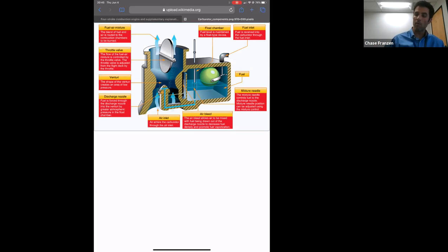Normal position is both, and that's just a very simple 4-way selector valve on the bottom of that fuel selector. There's no complicated machinery or electronics. You're literally moving that selector as you select it, and the valve is opening or closing. It's gravity fed, as we already talked about. So gravity is the only thing taking the gas from the wings down into the fuel selector and then ultimately into the carburetor, into the engine.